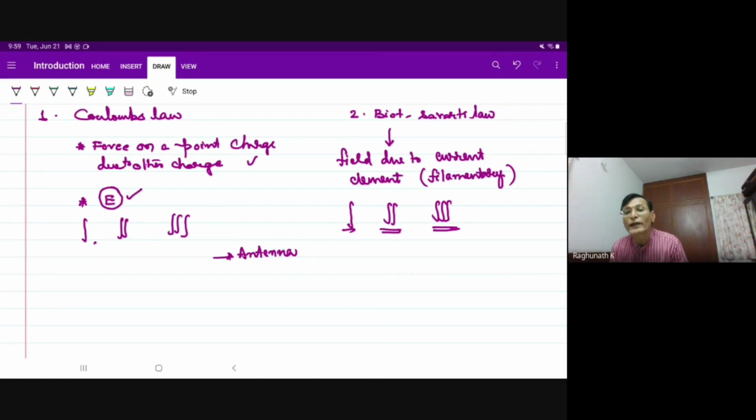No antenna is a point. But the first thing that we study in antennas and wave propagation as a topic is the Hertzian dipole, its radiation characteristics. Then every antenna's radiation characteristics are obtained by integrating that particular quantity, depending upon the way in which the antenna is there.